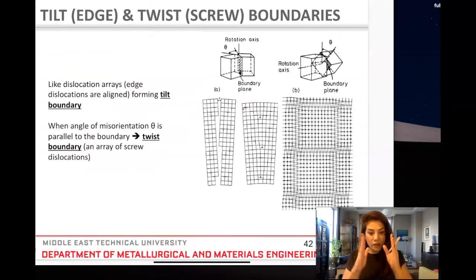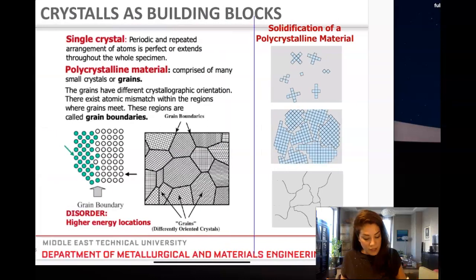So these grain boundaries can either be tilt or twist type. We've been taking a look at these grain boundaries as if it's a cross section, right? So these grain boundaries seen here, it's a cross section that you're looking at. They are actually, just like in the pomegranate example, three-dimensional crystal domains. They're not just a flat plane that you see on the paper. We just cut through and take a look at the planar view, but they do have a three-dimensional quantity, right? It's not only a planar quantity.